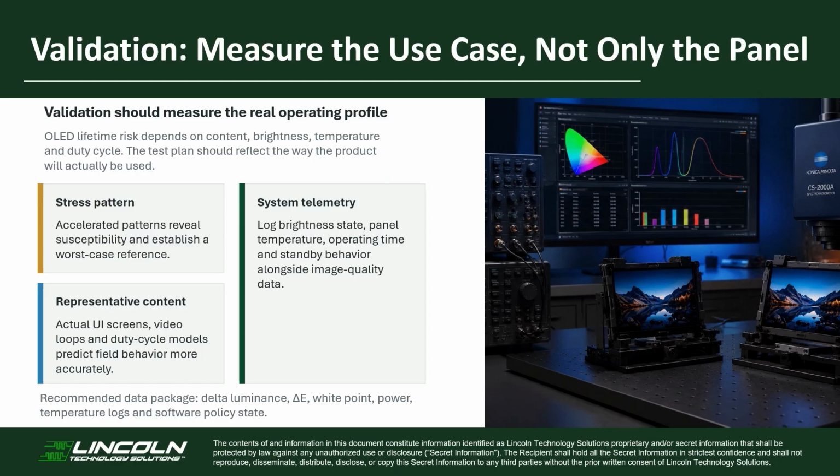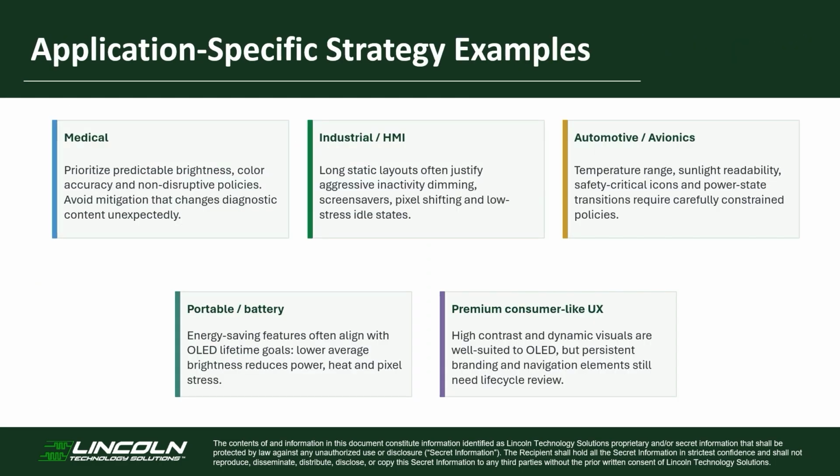The correct policy will also depend on the application. There is no universal mitigation profile. Medical applications may prioritize predictable brightness and color accuracy. Mitigation must not alter diagnostic content or introduce unexpected visual changes. Industrial HMIs often have long static operating periods, so inactivity dimming, screensavers, pixel shifting, and low-stress idle states may be appropriate. Automotive and avionics applications add wide temperature ranges, sunlight readability, safety-critical graphics, and complex power state transitions.